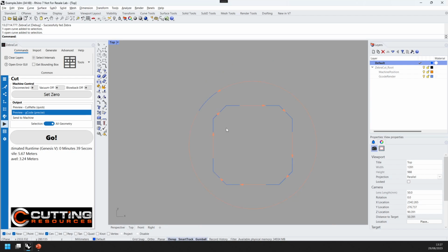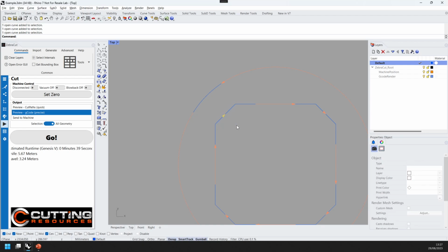So there is an element of experimentation required or measuring required on your blade to account for its properties correctly. But microcuts will allow you to essentially do a plunge cycle on very short curves like those. So that's dealing with overcutting by introducing undercutting.